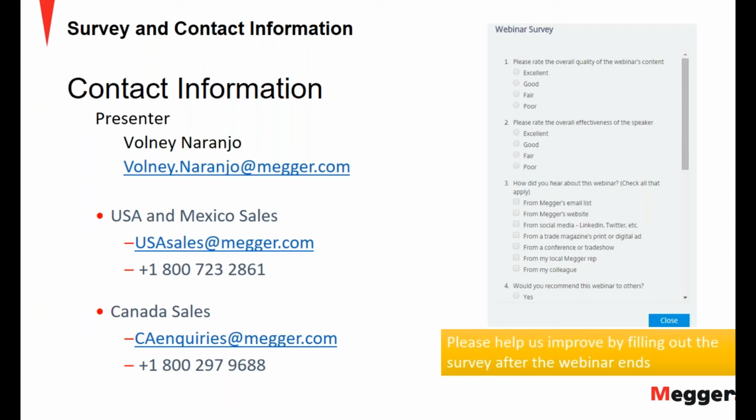If it's set at a higher value, that will result in overcharging of the battery, which will lead to excessive current being drawn, damage to the battery, and loss of capacity. On the other hand, if the voltage is set at a lower value, that will result in undercharging of the battery, and over time the battery charge will drop. Both scenarios are not good for the battery. The output voltage of the charger needs to be set at the right voltage, which is the float voltage, and the current that flows through the battery when the charger applies the float voltage is called the float current.